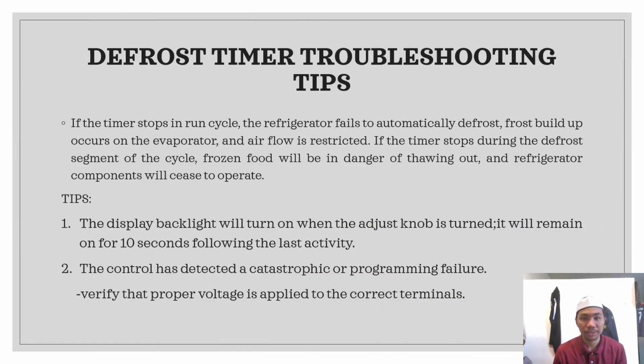Defrost timer troubleshooting tips. If the timer stops in the run cycle, the refrigerator fails to automatically defrost. Frost buildup occurs on the evaporator and airflow is restricted. If the timer stops during the first segment of the cycle, frozen food will be in danger of thawing out and refrigerator components will cease to operate.